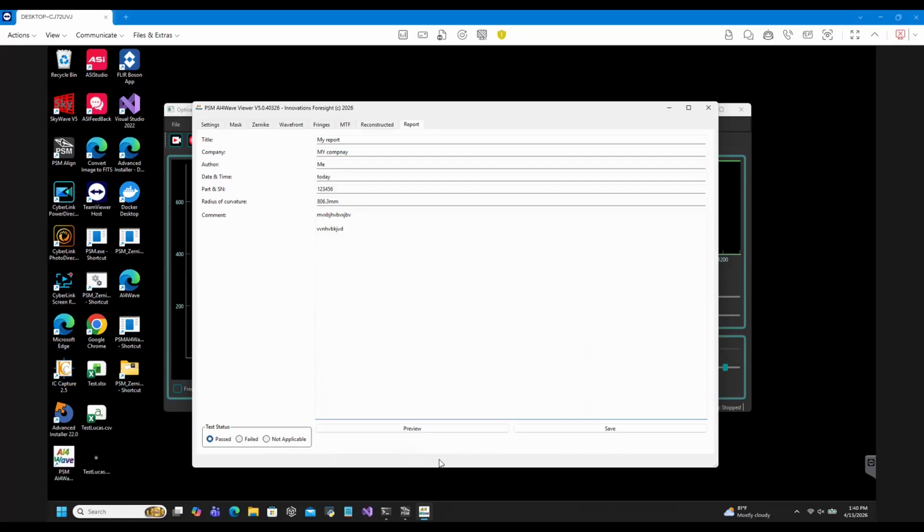Well, if you use the PSM like now, yes. But it could be used on a concave, convex too. You can use the PSM to look at flat optics. To do that, you have to remove the objective. And you can use the PSM to measure also a convex one, as long as you have enough working distance with the PSM macroscope objective. After that, you need to put an optic to address the problem of convex surface with the PSM. It has nothing to do with our technology, though. It has to do with the way the PSM optics works.